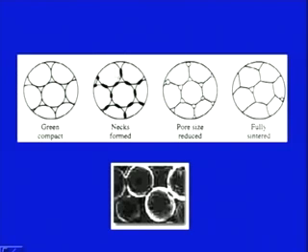For example, these two metal particles are meeting over this face, and here a neck formation is taking place. The pore size, or void size, has been reduced and particle to particle bonding has taken place, and this is the total length of the bond developed between two metal particles.